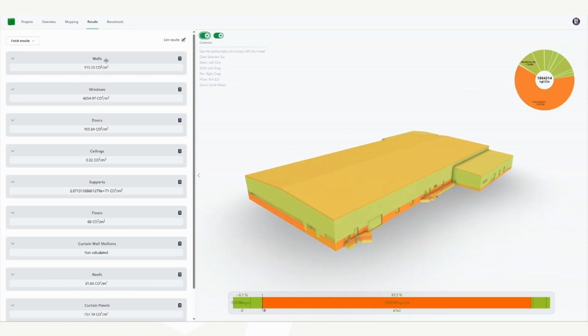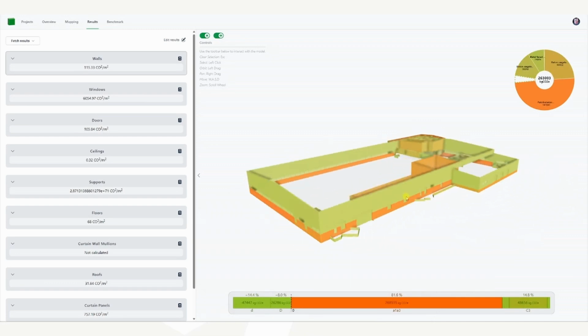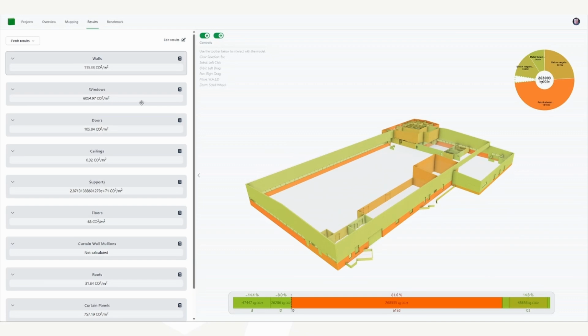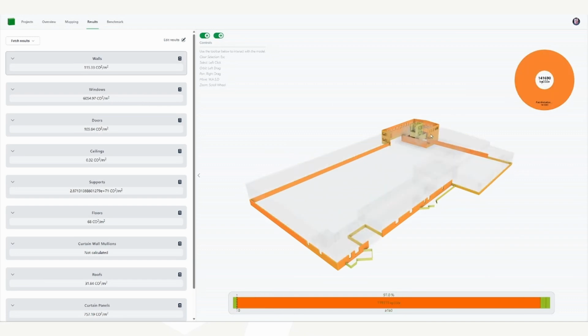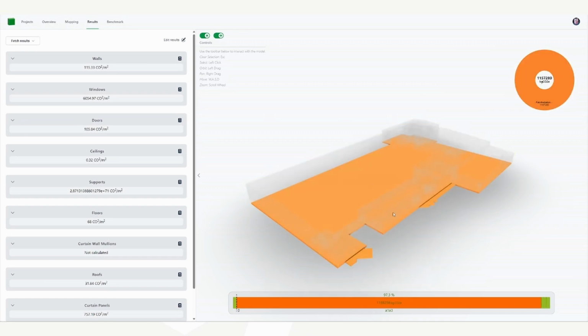So using a wooden construction, where are the actual emission values in the model? So you can see in red here that you have a concrete foundation slab in the bottom that is very problematic and has very high emissions. So if we can change that out, we will gain very big gains in carbon emission.